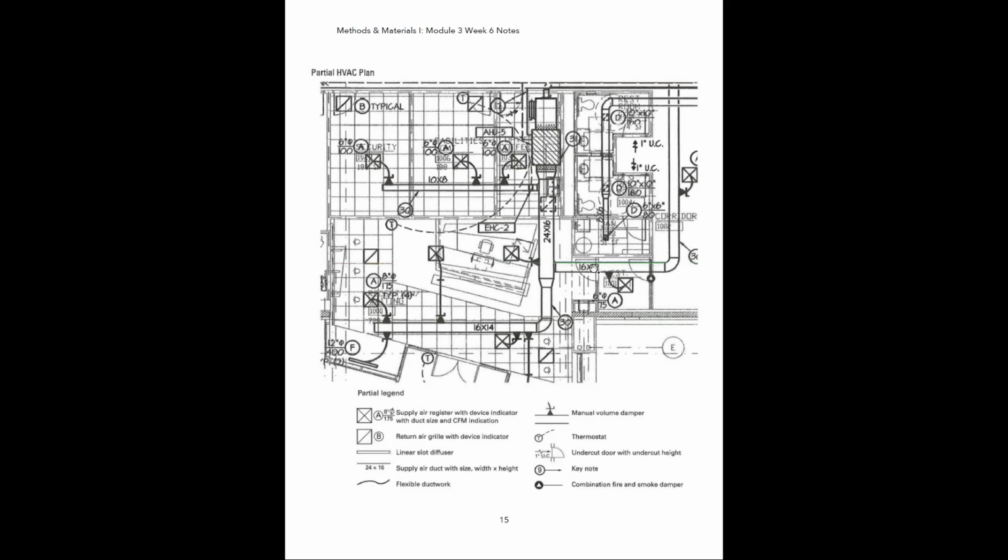So that ductwork is likely penetrating that gypsum wallboard that is above this curtain wall assembly. And where that penetrates by code, we're going to have a damper, okay, that is going to automatically close when there's a fire. When it senses a fire, it's going to shut that damper closed, and it's going to prevent that fire from spreading throughout this ductwork that's in here. All right, so that's indicated right there with that little triangle.